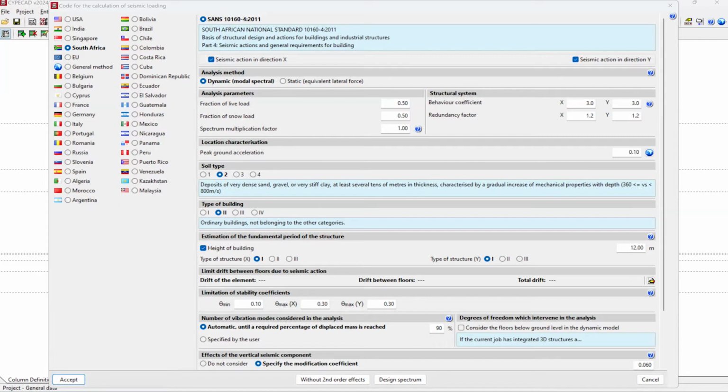Yes, that's correct. I think since we've been experiencing high magnitude earthquakes, in terms of South African structures, we need to take the seismic load into consideration. Even if you are doing a single story, the other issue is that normally, in the way buildings are constructed in South Africa, they ignore columns. And columns in a structure are the ones that play a vital role in terms of earthquakes.